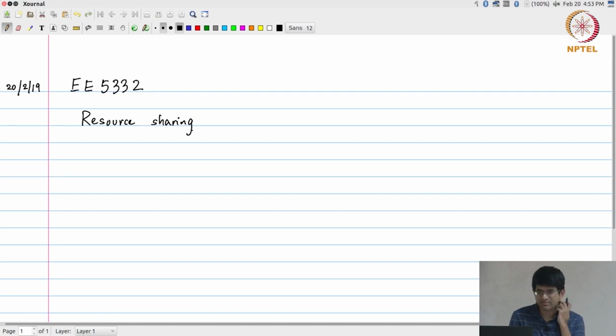Okay. To understand this better, let's start with a very simple example and then we will move on to a more complex example. The example that I am going to consider is just y of n equals a of n plus b of n plus c of n. The trivial fully dedicated architecture for this system would look something like this, assuming that the hardware available to me is adder blocks that are capable of adding 2 values at a time. That is a fundamental assumption that I am making over here.